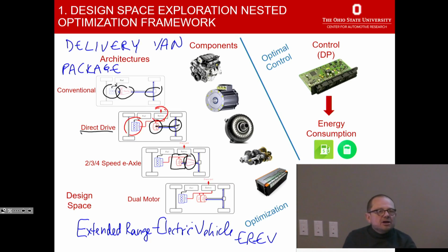And by having a multi-speed transmission, my performance will be better. At 0 speed, I can be in first gear, have better acceleration. If I need to go on the highway for a stretch of time, I'll go to a higher gear. There is a reason for transmissions, right? And I still have the same genset here. That part hasn't changed, but now I have to decide 2, 3, 4 speed, okay?